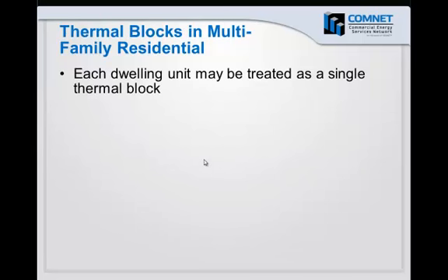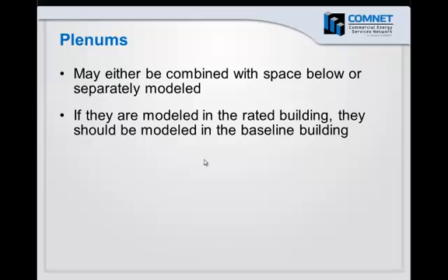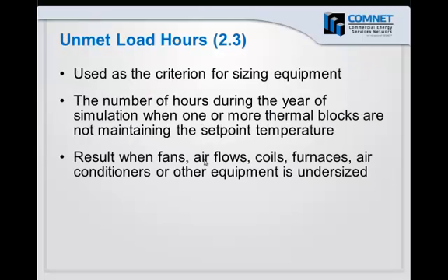The rules for multifamily are that you can basically take the entire dwelling unit and model it as a single thermal block. Plenums can be either modeled or not modeled, however they're treated, though, they need to be treated in the same consistent way for both the rated building and the baseline building.